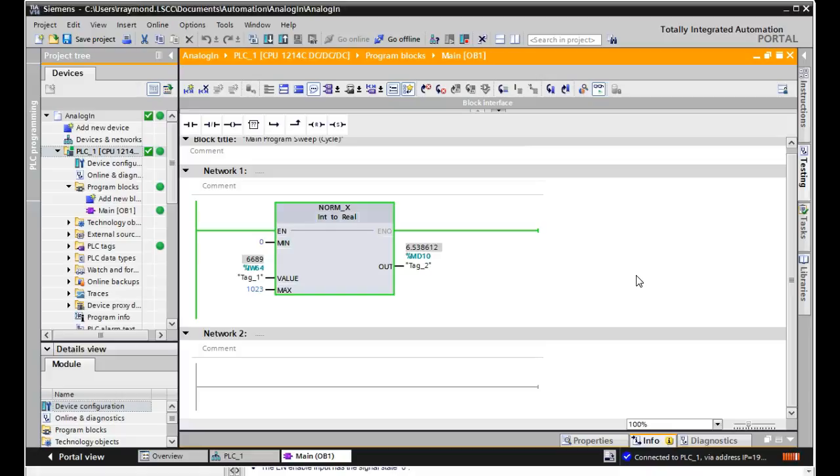So what this is automatically doing for me is taking this value, which is coming in from my pod, and converting it over to this value coming over from the transfer function. If I was to take 10 volts and divide it by 1,023 and then multiply it by this number, this is what it would do. And it's doing that for me automatically. Right? That makes sense?